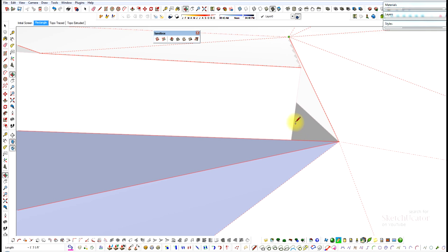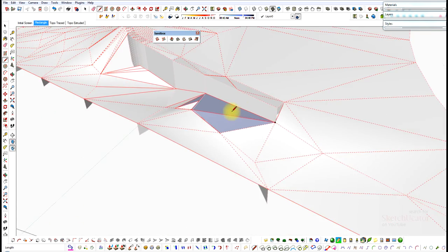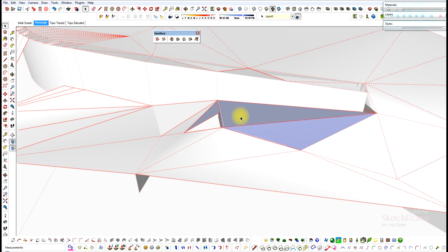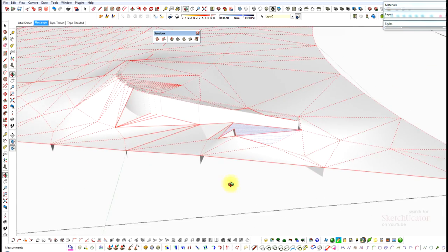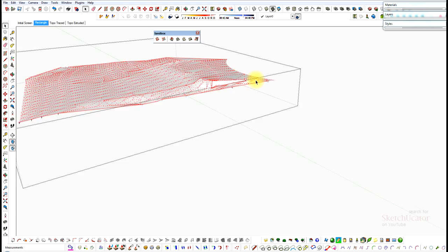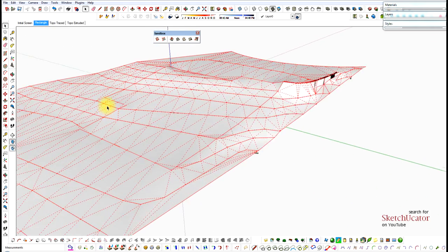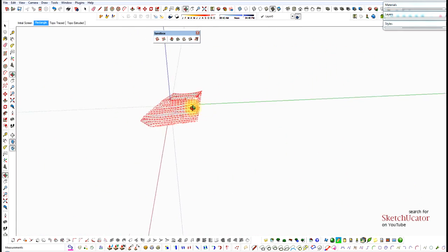See, what looks like it's attached isn't necessarily attached. So we can keep doing that on and on. I can reverse these faces if I like by selecting them, right click, and reverse face. So I get rid of that kind of goofy stuff that's going on there. So what we've done is created steps, we've created the topography, and we've superimposed the house profile on there.